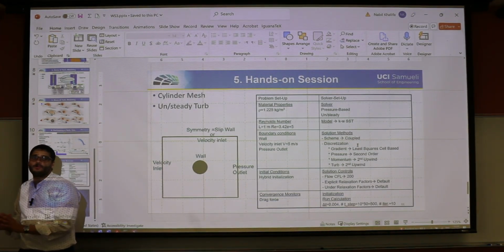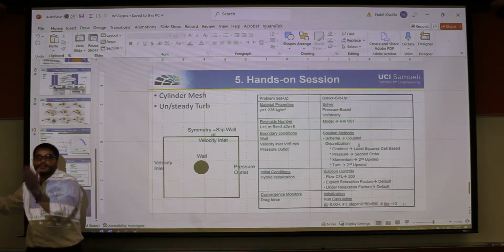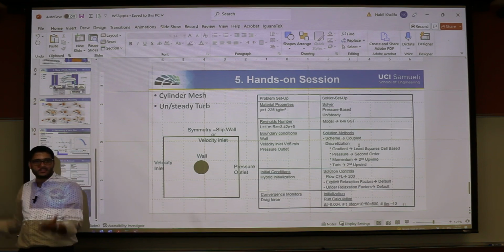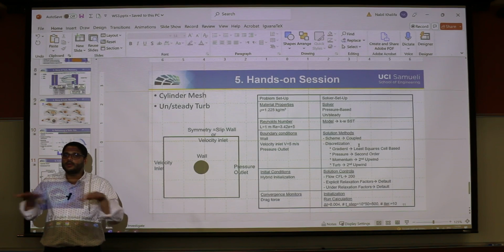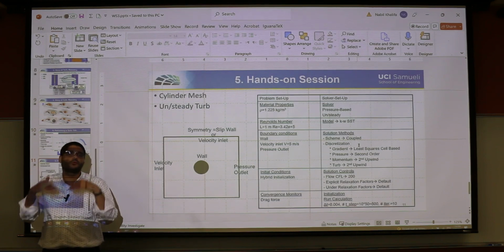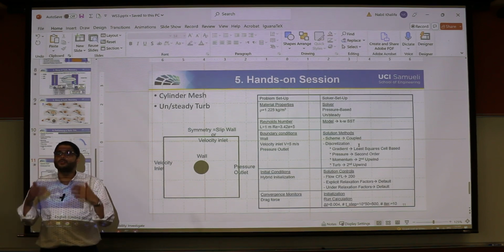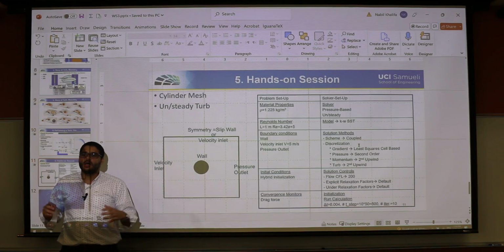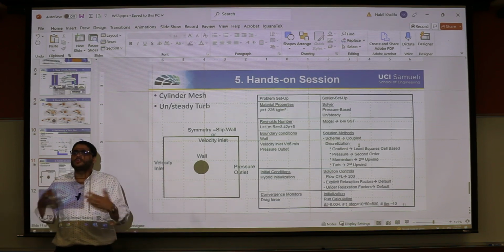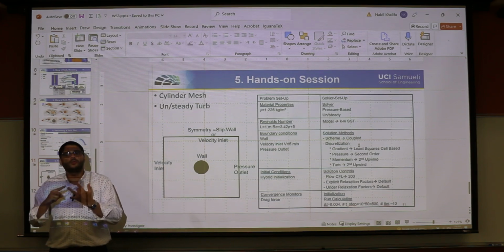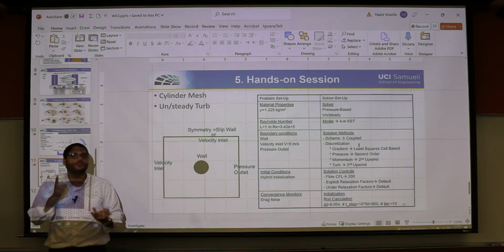If you reach that step, then you're good to go to just take all of this case and data file and this Fluent setup and send it to the HPC. So it doesn't need any CFD or fluid or physical information from you or anyone to be able to do that. It just requires a long time or a huge amount of patience to be able to deal with the Linux system, to deal with the Fluent software from the text user interface instead of the graphical user interface.